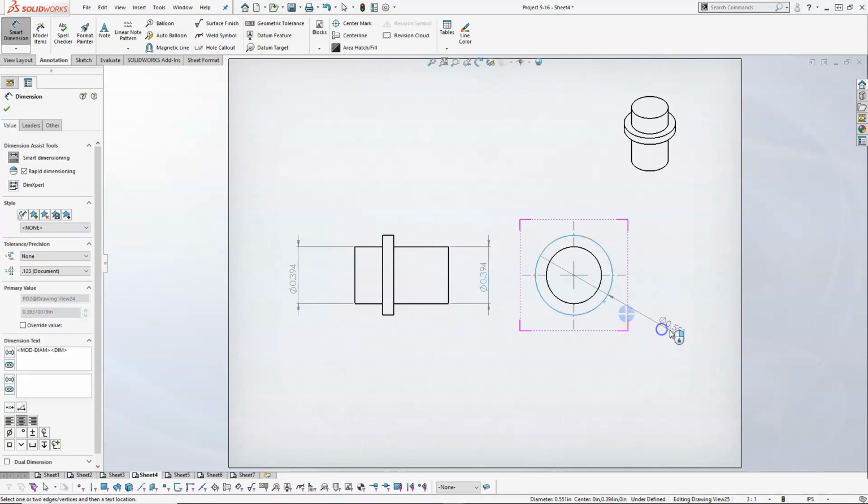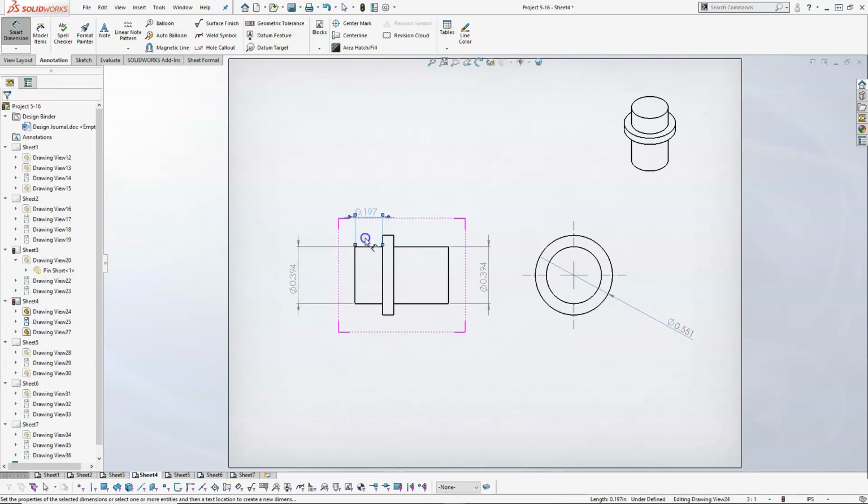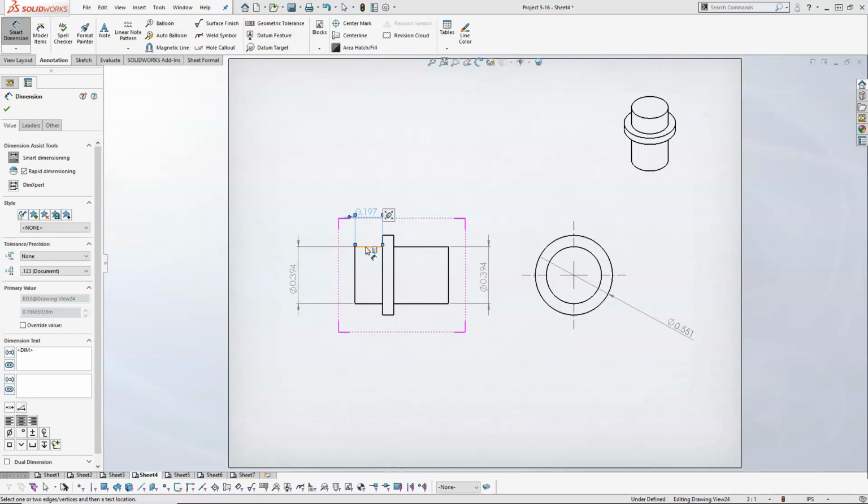And we'll apply a few dimensions. Alright, so again I can pick the geometry, that little symbol that popped up. Let's see if I can get it again. That's called a silhouette edge. And what it's doing is where the plane passes through the cylinder, it creates a line at the top of the cylinder and a line at the bottom of the cylinder. So silhouette edges are something that's pretty handy that we'll be able to utilize later. Alright, and then we get our overall.